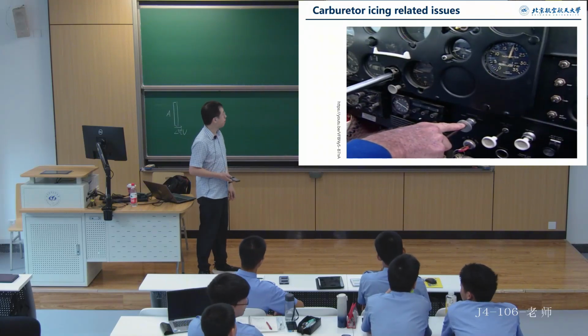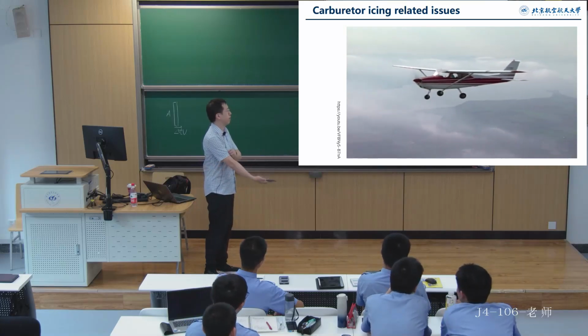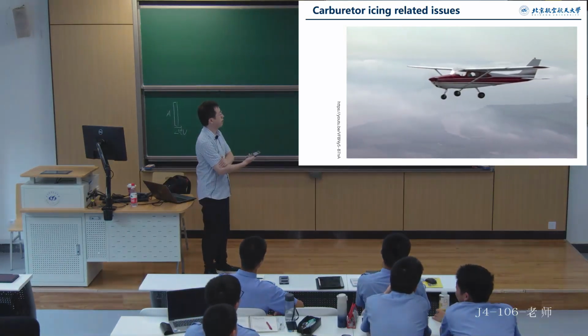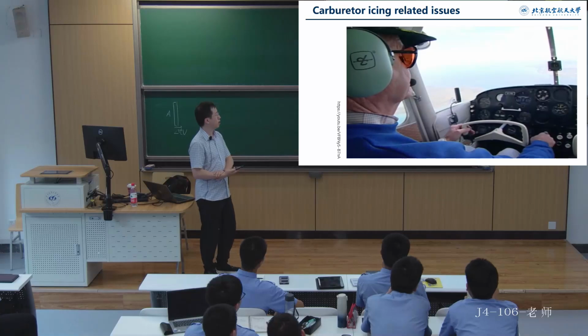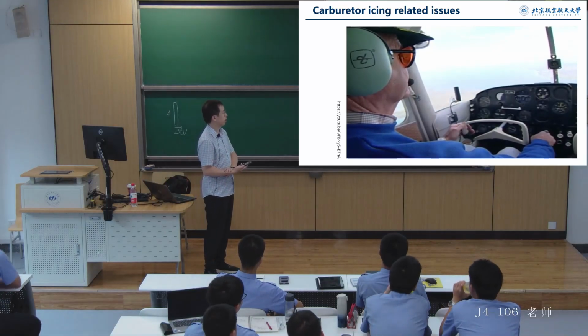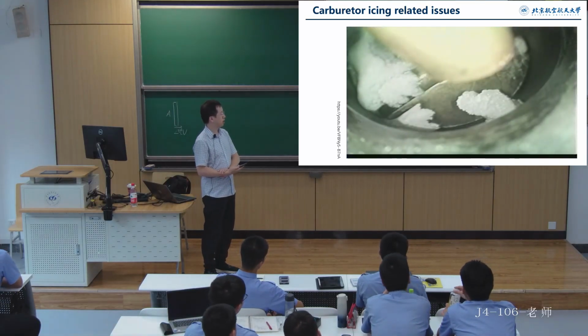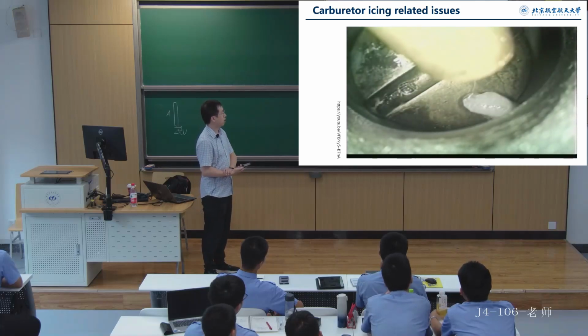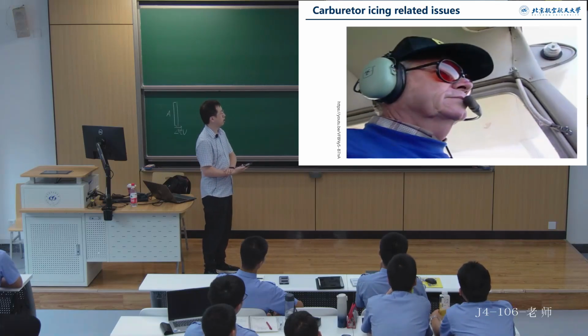Full power to return. It may be necessary to adjust the mixture to smooth out the engine, so consult your flight instructor for proper usage. If you do have carburetor ice, be prepared for a further loss of power when carb heat is initially applied, as water from the melting ice is drawn into the engine.